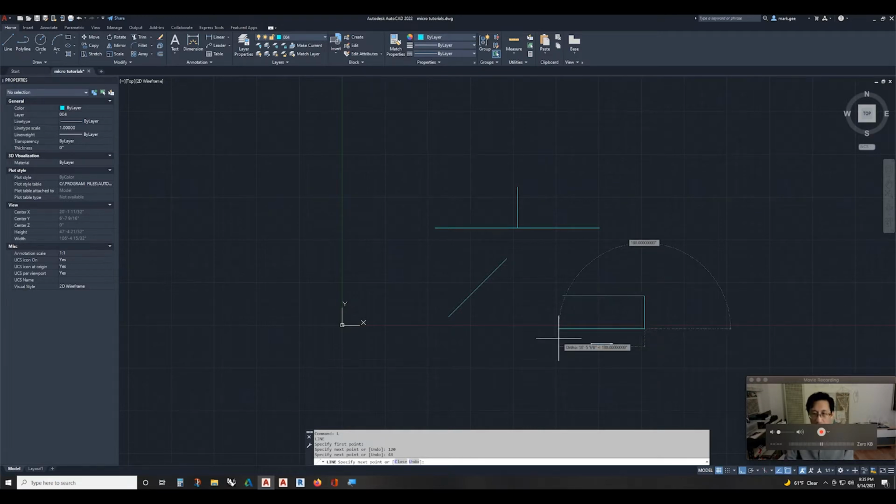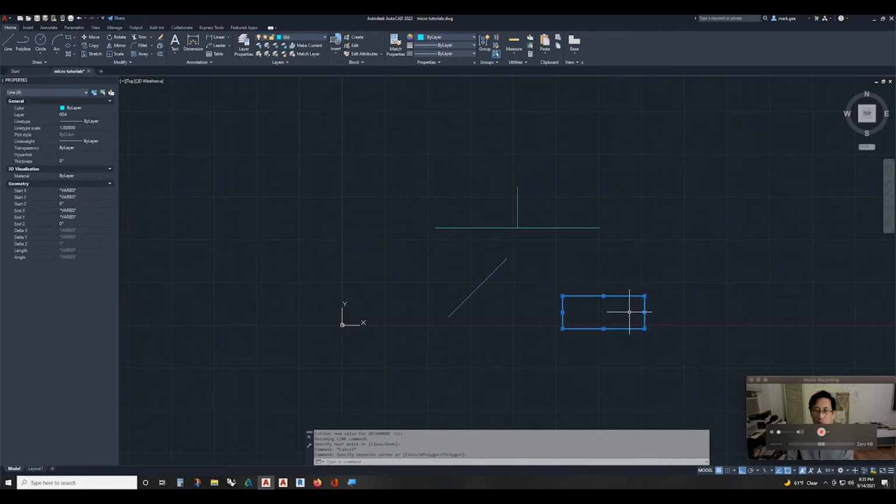You can come across again, and in this case, I'm going to hover over that first point and pull off. You see the green line there? That's an object snap tracking guide. And so AutoCAD has snapped there. It's pulled off a guide, and I'm going to click there. And now click back at the starting point, the command is still active, space to end it. So I've just drawn 4 lines. These are 4 separate lines here to create this box.